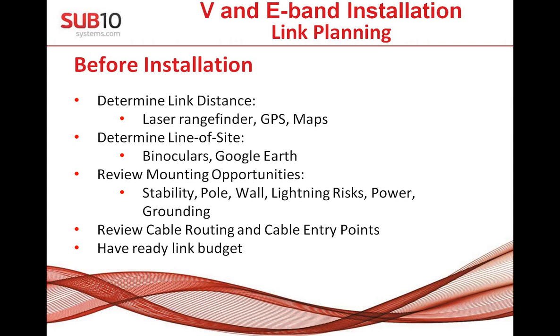Lightning risk: be sure whether it's good to install lightning protection or not. You have to be sure that power is available where the power injector will be located, because sometimes it's not in the server room, it's in some small box somewhere on the house, even on the top floor. And the last option, grounding.